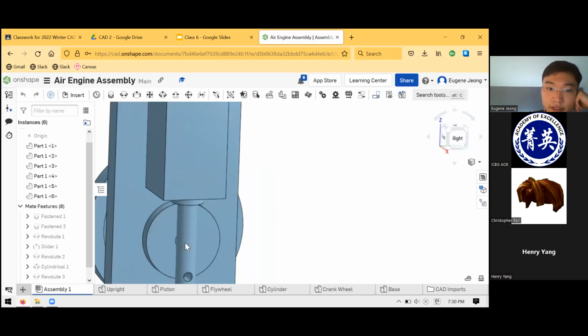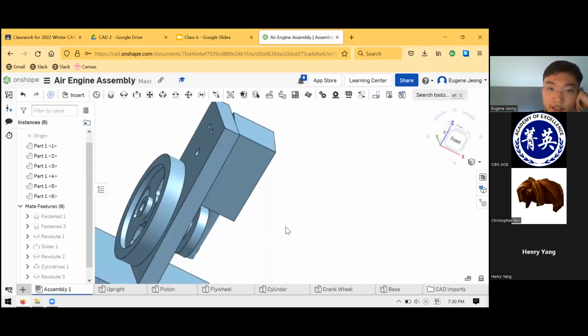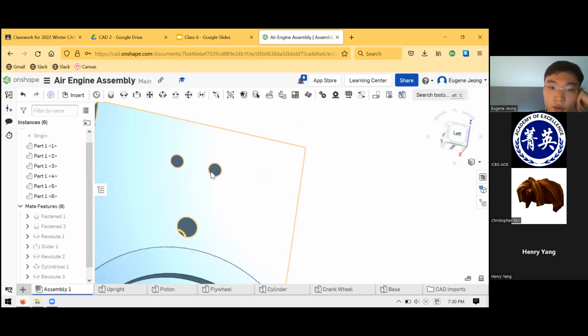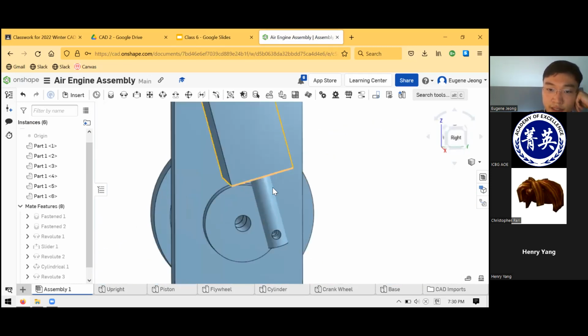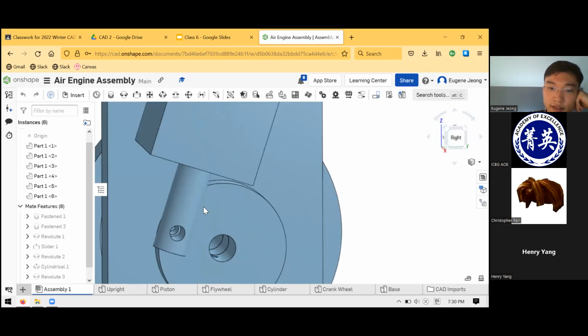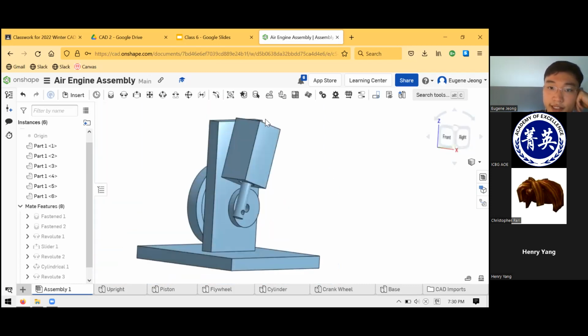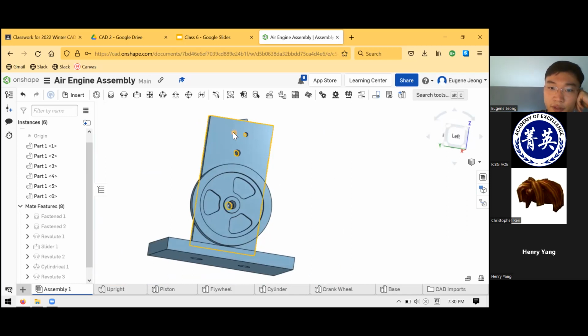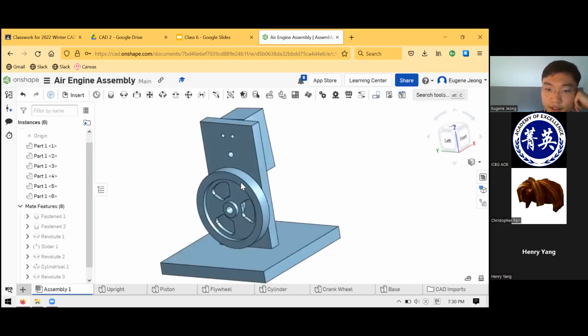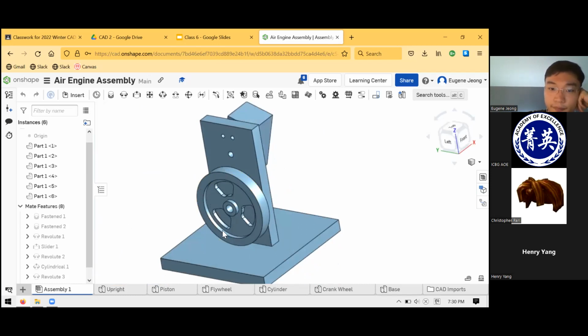And as that happens, it rotates, gets into this configuration, and then these two holes line up. The air that's in the cylinder is going to be let out of this hole. And so as that happens, the piston kind of is able to get drawn back in a bit. And so it just goes back and forth between those two states. It's either getting air from this hole or letting air out of this hole. And as it continues to do that, it just spins this, and the result is the spinning flywheel.